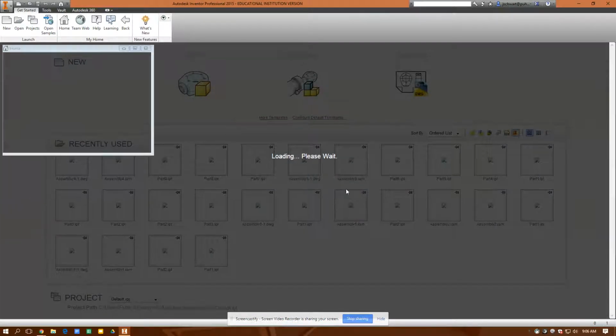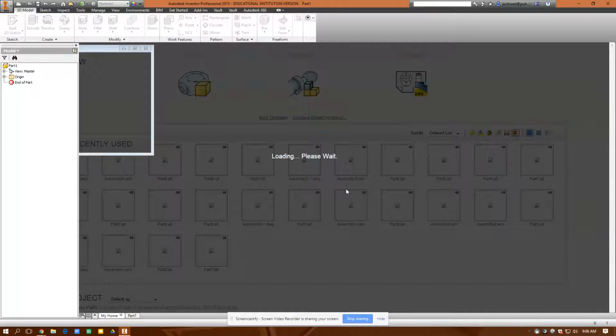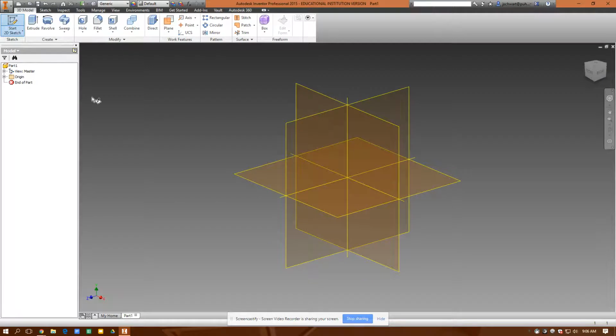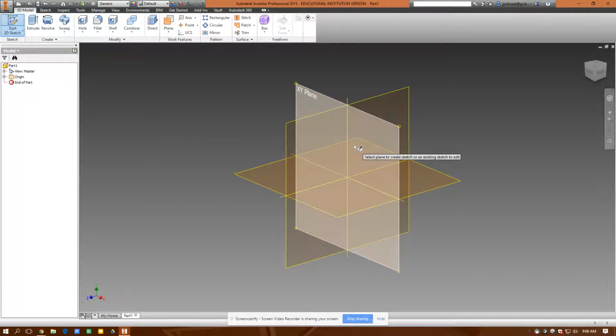You can draw it as a front rectangle or the side and extrude it out. But the way I think I'm going to do it is I'm going to draw the side view with that 12-degree bevel cut and then extrude it down to 12 inches. So I go up here, start a 2D sketch. I want to draw in the XY plane.